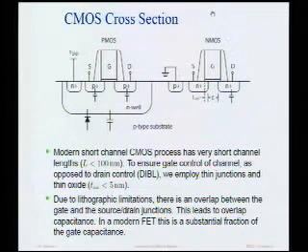In terms of high-speed performance, we know, and we'll review that briefly, that using shorter length devices is a big advantage. The shorter we make the channel length, the better. And probably the advances in integrated circuit technology for the past 20, 30 years has all been about making that channel length shorter and shorter through lithographic technology. In fact, today you can go out there and buy a transistor with 90 nanometer channel length. Actually, the effective channel length is even shorter. It's about 60 nanometers. So we're talking really tiny channels here.